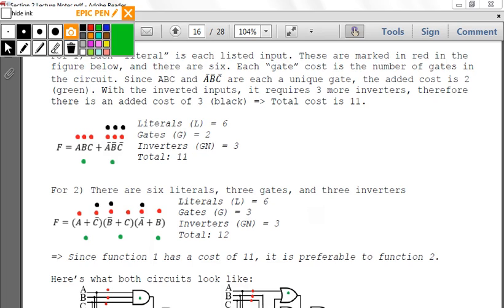Does lower cost always mean faster? Remember the 4 design principles? Smaller is faster. Smaller is always faster because it's going to go through fewer transistors, fewer gates to get to the output. But faster isn't necessarily what you want because you want to prevent those race conditions.